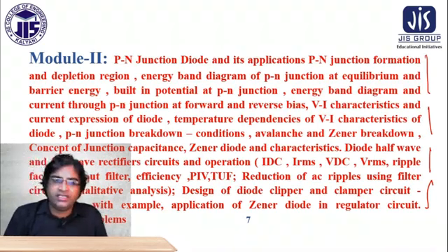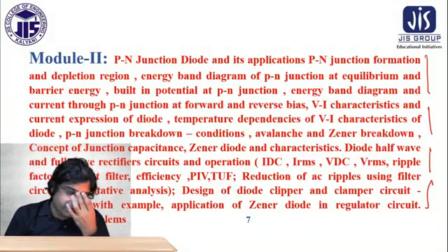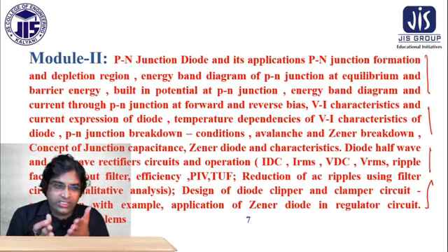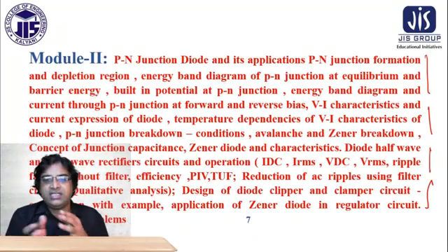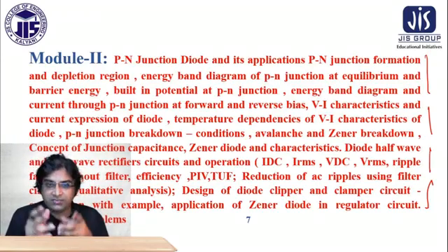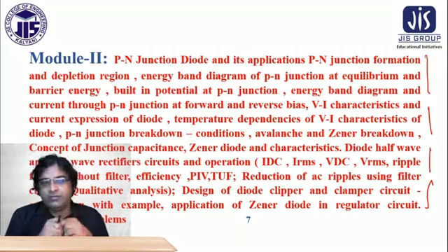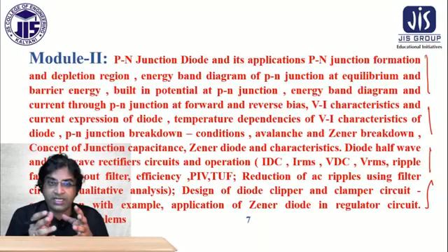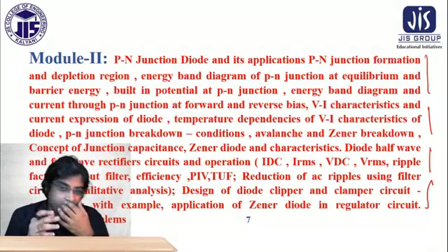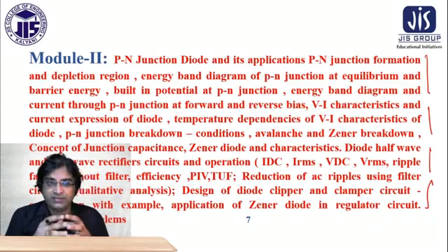And then after that, there are half wave rectifiers. What is actually the concept of rectification, how we can convert an AC signal to a DC signal? This is very, very important in this portion, and also the full wave rectifier. There are several kinds, the center tap concept of the rectifier and the bridge rectifier concept. So half wave, full wave, different kinds of rectification we can study.